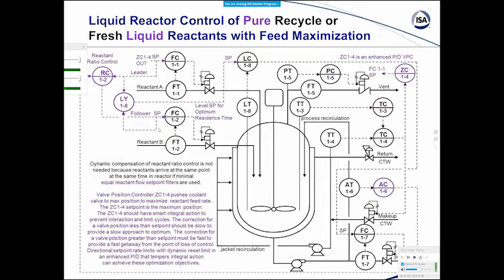So you really want to tune these flow controllers for the best response on their own, as fast as they would do with robustness, so it's not oscillatory. But in order to coordinate it, then you put a set point on the filter as you're going to change production rates. You can say, well, set points is bad in cascade control systems, but here we're talking about changing production rates. And you would have equal set points.